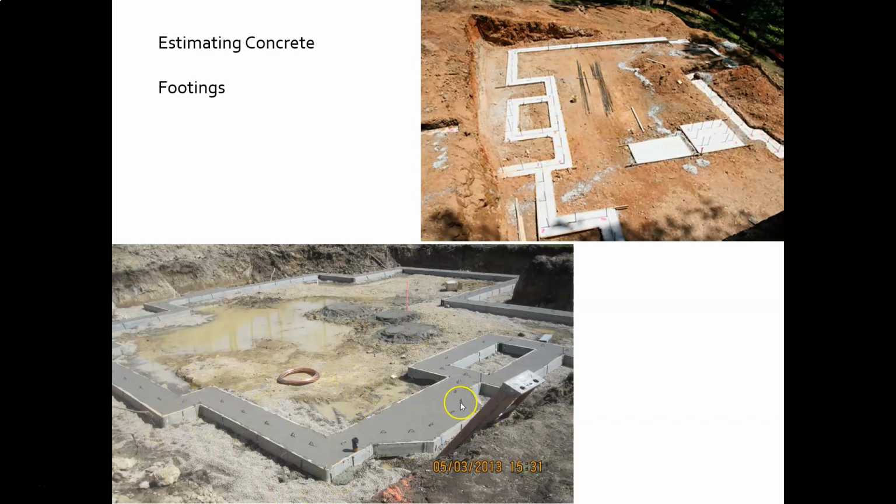And here we have formwork. So again, we would have to calculate all of this linear feet, and here we would want to capture that corner, and then here we would capture that corner, and it looks like there just might be a sliver in between them. So we don't want to double count. Or we could count this length and then stop this one here, and then we could make this a wall. Either way, it ends up at the same thing. And here's a foundation for a bay window or something like that, so we would have to calculate that additional piece as well.